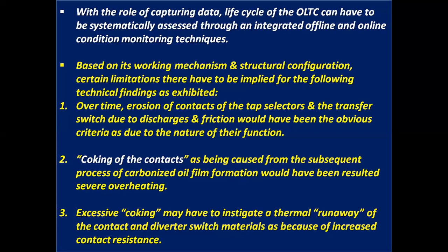Coking of the contacts. Coking of the contacts is caused by the subsequent process of carbonized oil film formation, which would result in severe overheating. Excessive coking may instigate a thermal runaway of the contact and diverter switch materials because of increased contact resistance.